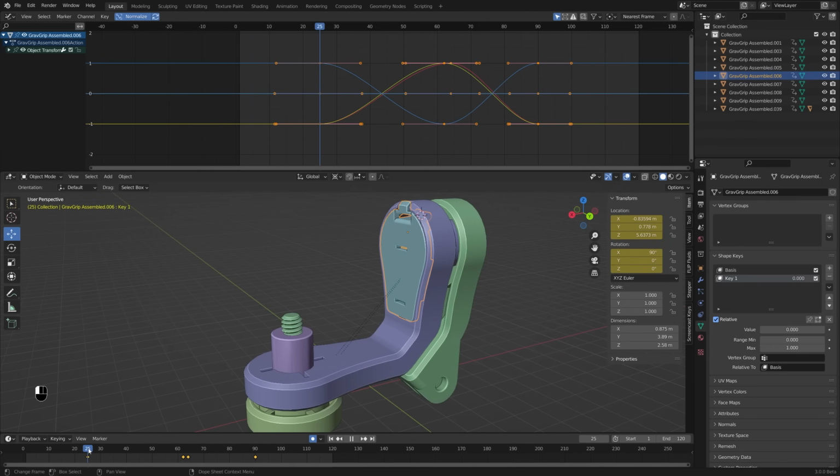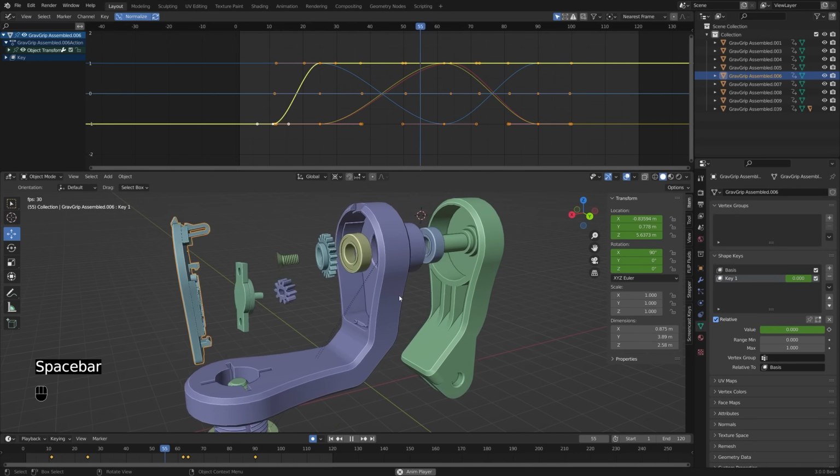That animation doesn't start until frame 25. So maybe at frame 25, we have this fully depressed, insert keyframe, and then we'll pull it back a little bit, and we'll have that back to 0. With my auto keying on, it is automatically adding a keyframe for me, which worked a little bit weird. Be careful using that auto keying. Sometimes you can accidentally insert keyframes when you don't want to.